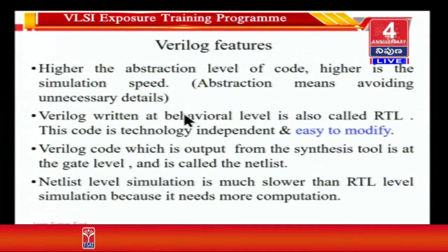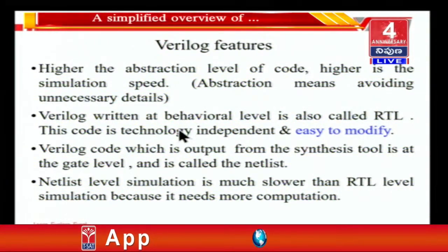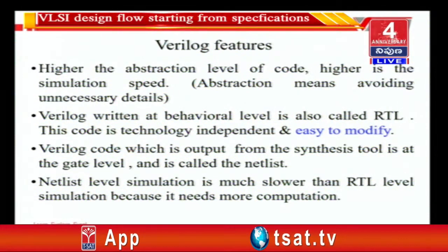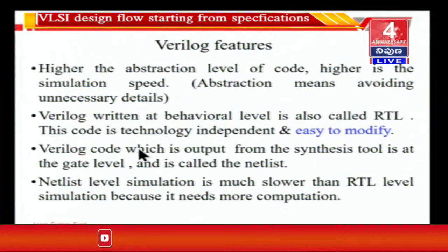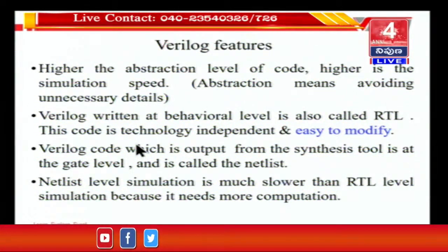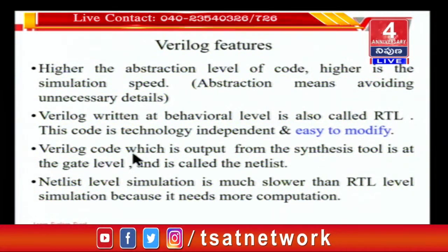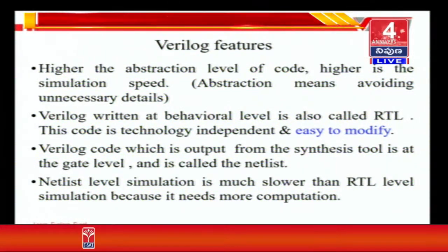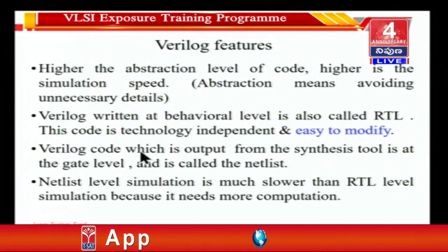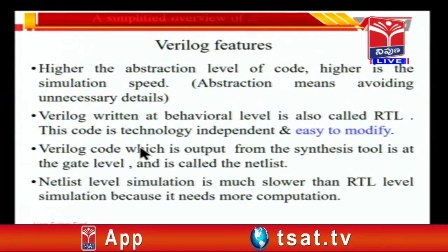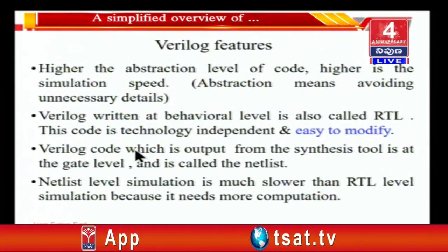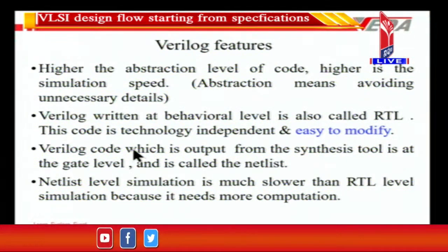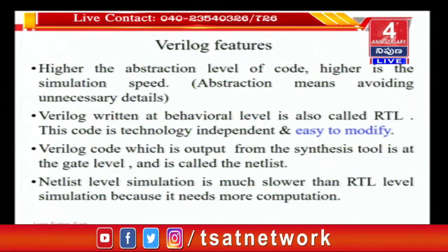It's pure functionality. Timing will come into the picture only when it has been synthesized and the logic elements have been picked up from a technology library. These logic elements will be actual physical logic elements whose representation is identical to its behavior in hardware, but right now it is a representation in software. Right now means in the library it is a software representation of a hardware behavior.